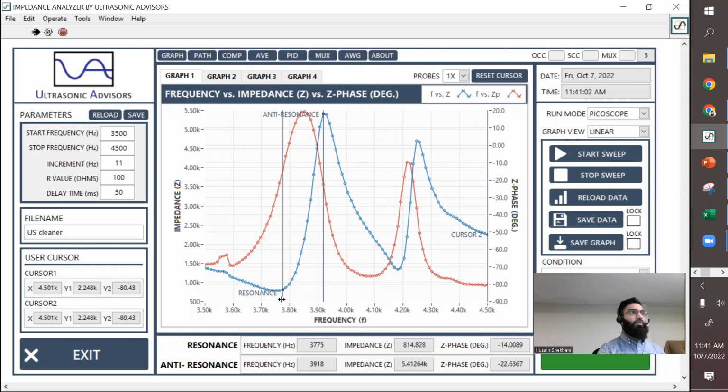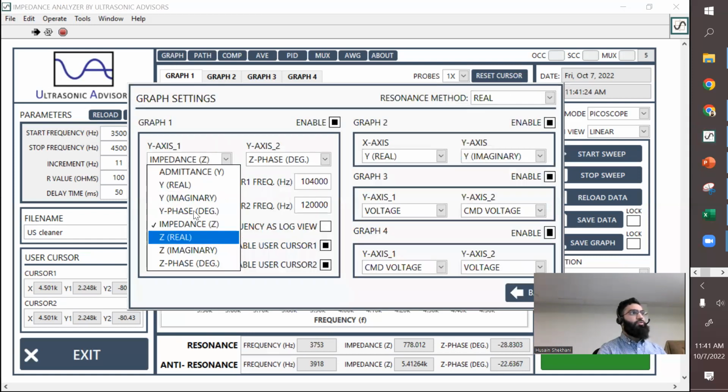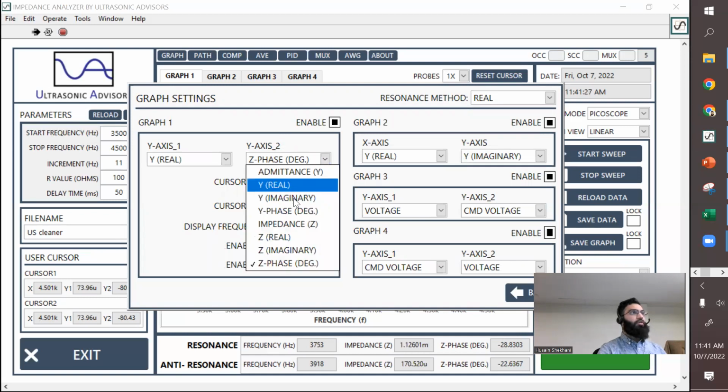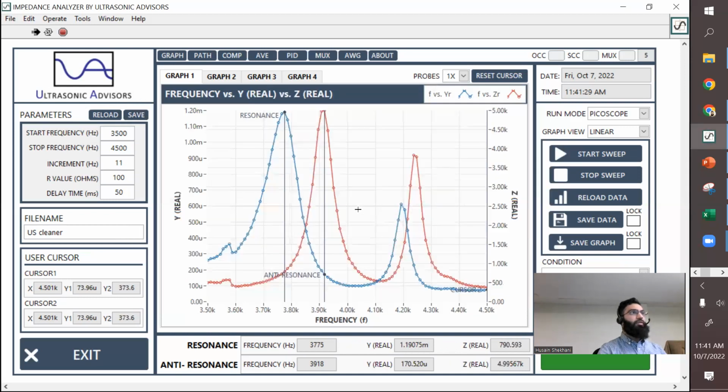Now, this is a real prime example of when it just feels wrong to use the 3dB method here. Something probably in your heart tells you that this is not right. And trust your heart always, right? So what to do here? In your impedance analyzer, you would change your function, but here, this is how I change it to real conductance and resistance. That's a lot nicer to measure. What do you guys think? This is a lot better to measure for quality factor and for resonant frequency.